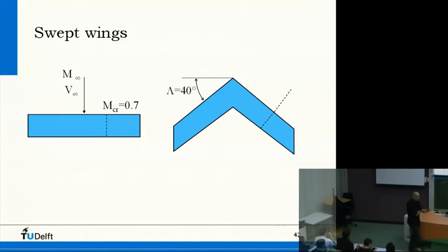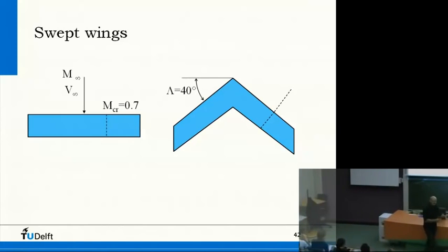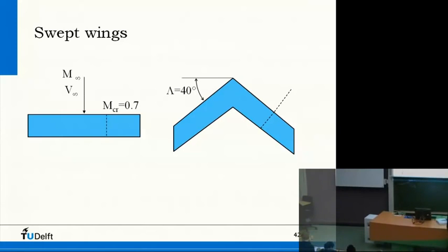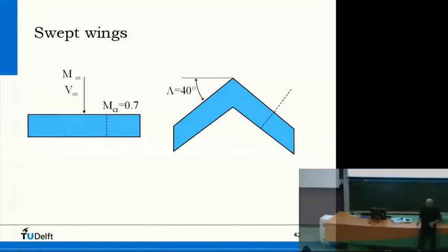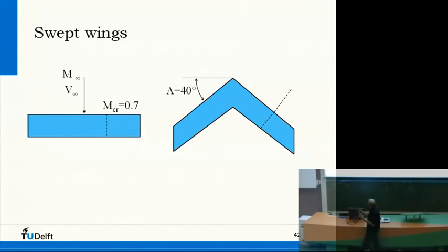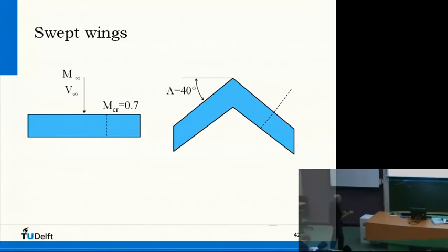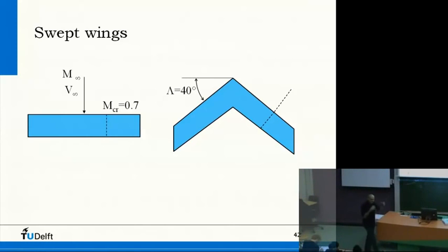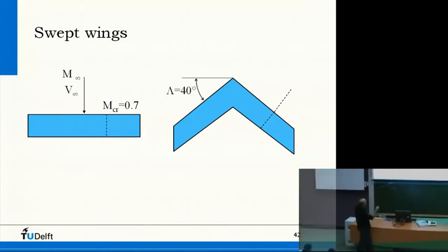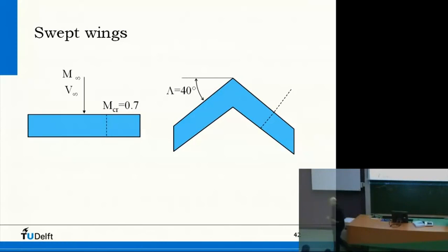Okay. So we have this wing concept. We have a wing, the effect of the wing is that there's a wing vortex and we have induced drag. Okay. But now, if compressibility comes in, what happens? So here we have this wing, and then they have this critical Mach number of 0.7. So somewhere on the airfoil, somewhere on this wing, we have Mach 1 at a flow of Mach crit is 0.7.